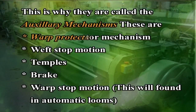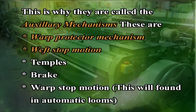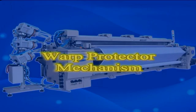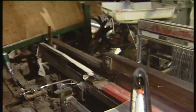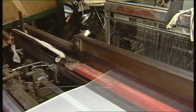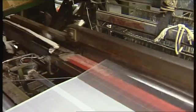These are the warp protector mechanism, weft stop motion, temples, brake, and warp stop motion. These are found in automatic looms. Coming to the warp protector mechanism, it will stop the loom if the shuttle gets trapped between the top and bottom layers of the shed. It thus prevents excessive damage to warp threads, reed wires and shuttle.